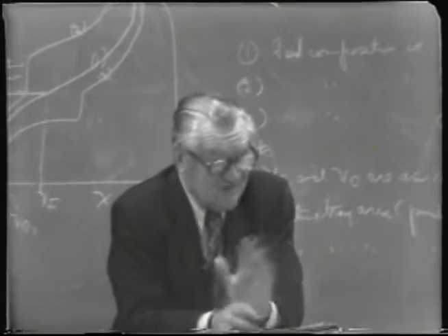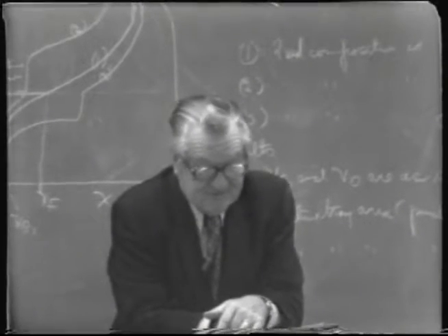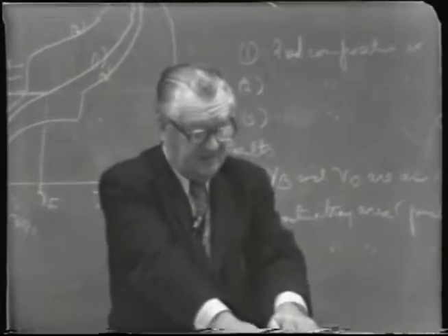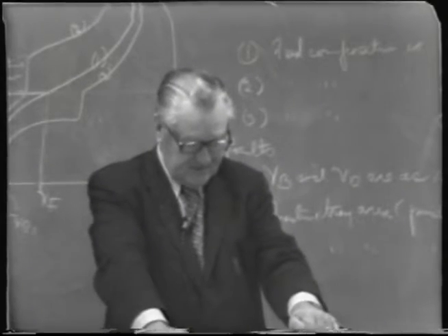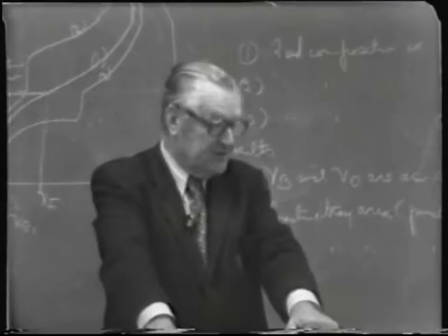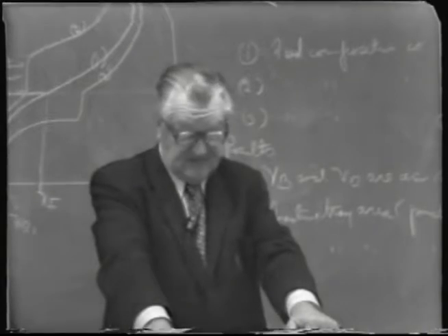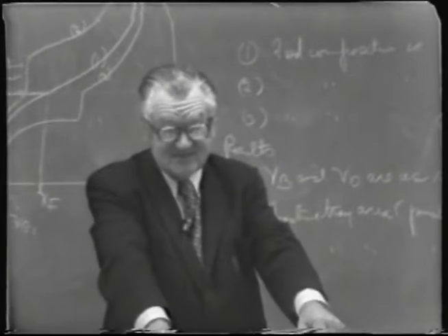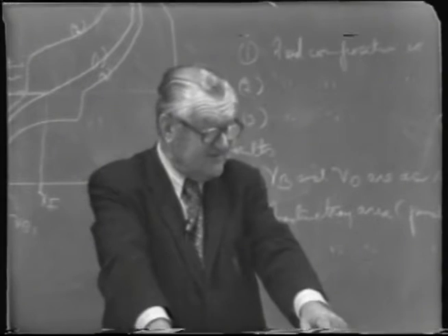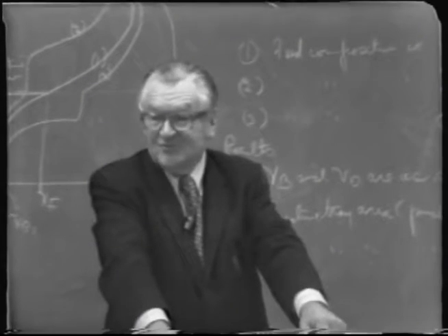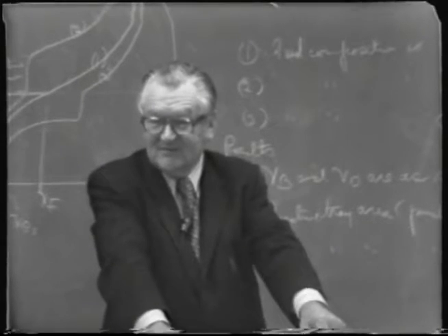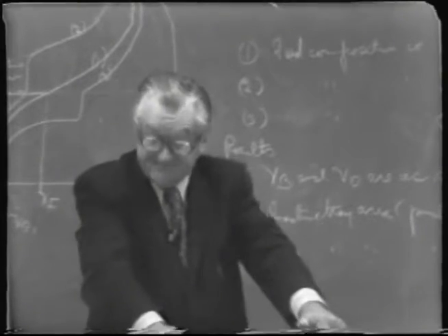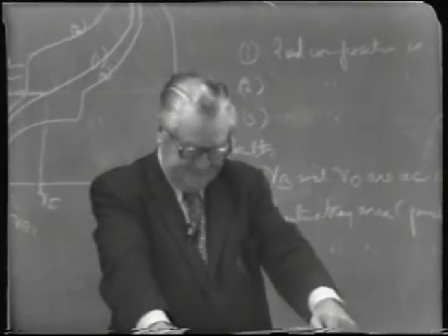In other words, most all the columns existing in California were always purchased with the capability or the intent of being able to distill 198 or 192 proof spirit. If you have 40 trays in the concentrating section, you don't have too much difficulty getting up to 192 proof. The top of the column, maybe 193 even, is not uncommon.